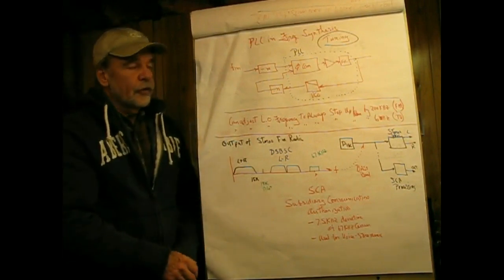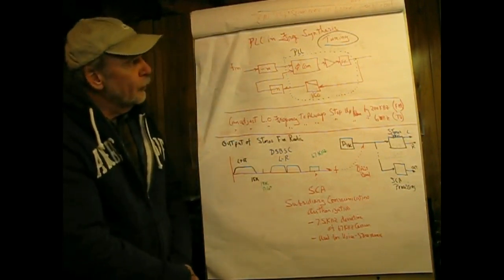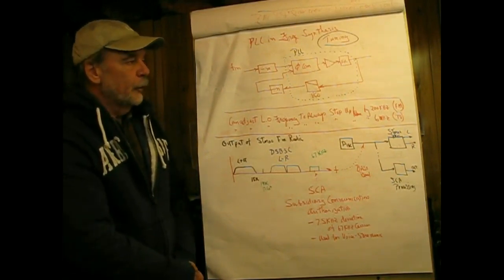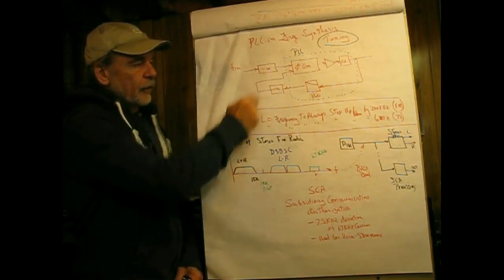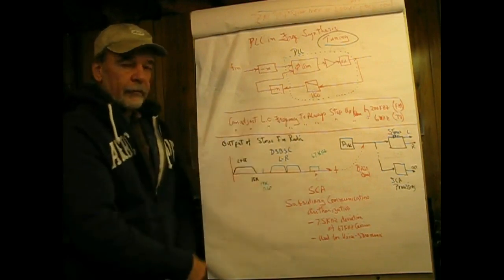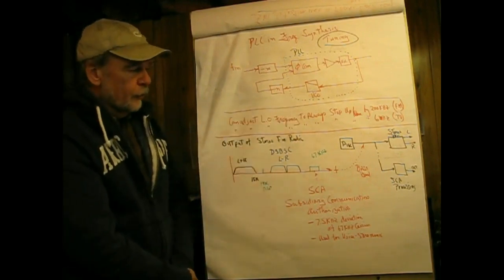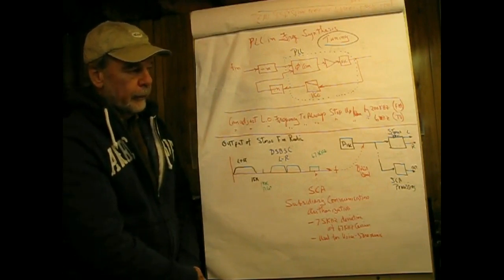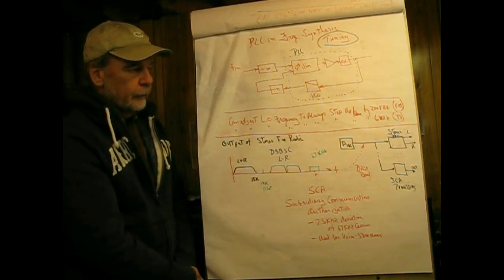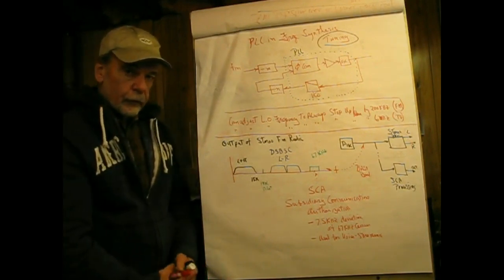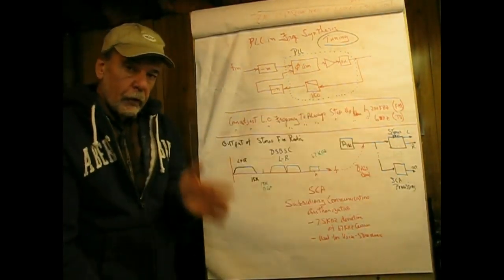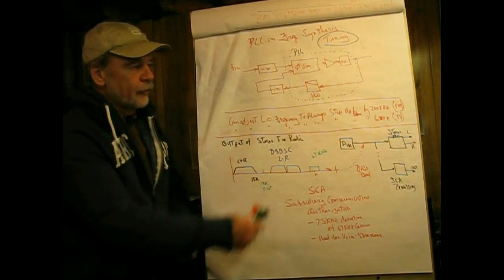Now we can also, and this is just an aside from FM detection, use a phase lock loop as a frequency synthesizer. And the way we can do that is by putting programmable divide-by stages on the input to the phase comparator and in the output of the VCO. Now what that allows us to do, say for example on our car radios or anything else with an up-down channel changing button, is when we push it, we change the local oscillator frequency for FM exactly 200 kilohertz. So it's always on station, and this is crystal referenced.